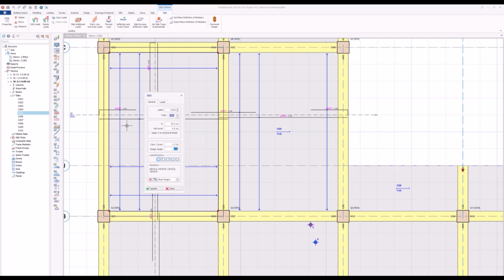We weren't including that slab in the finite element mesh, because when you mesh a slab, it will be distributing loads in two different directions. When you mesh it, it's against the one-way slab assumption. So that was why we weren't meshing those slabs.